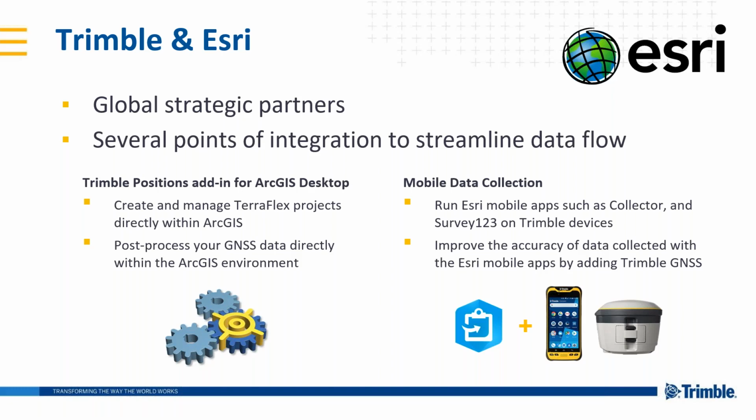So that's just one example where the technology across the companies can come together. And then on the left-hand side, Trimble develops an add-in for ArcGIS desktop called Trimble Positions. And from Trimble Positions, you can create jobs or create data collection jobs and send data from your GIS out to the field, to the Trimble solution, and then bring it back into your GIS as well. And one of the important points to highlight with Trimble Positions is that it gives you the ability to post-process your GNSS data within the Esri environment.